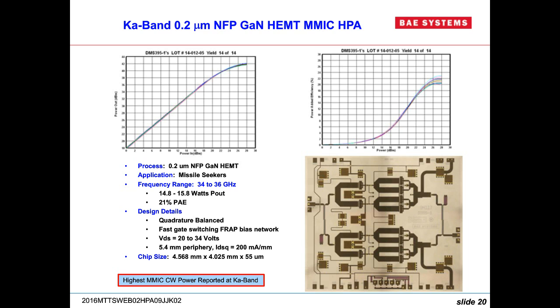But let me say this about CMOS silicon. Where it makes a lot of sense is after the front ends, where you can integrate, let's call it, all the control functions, where you might want to do phase, amplitude, IQ and down conversion, gain blocks, variable gain. That can become a super chip in silicon CMOS, and it makes sense to do those functions in silicon CMOS and not do them in compound semiconductors. So I just think it's a bit of a stretch.